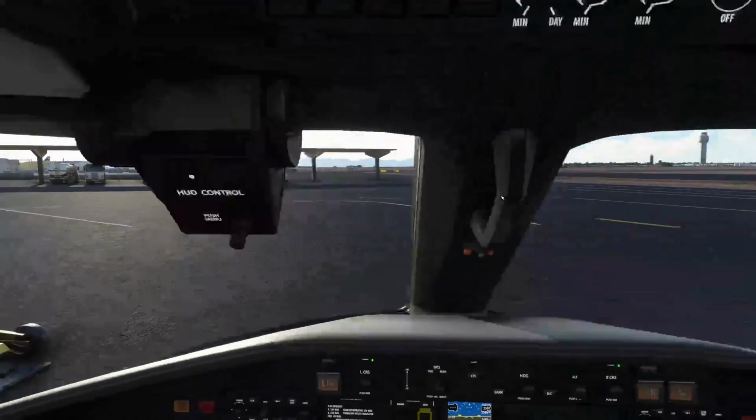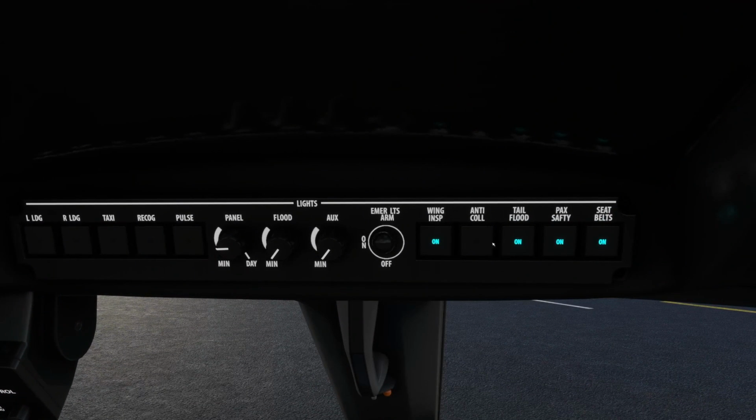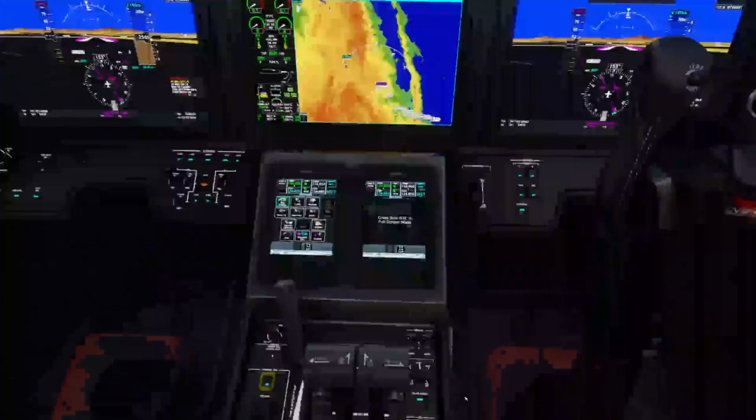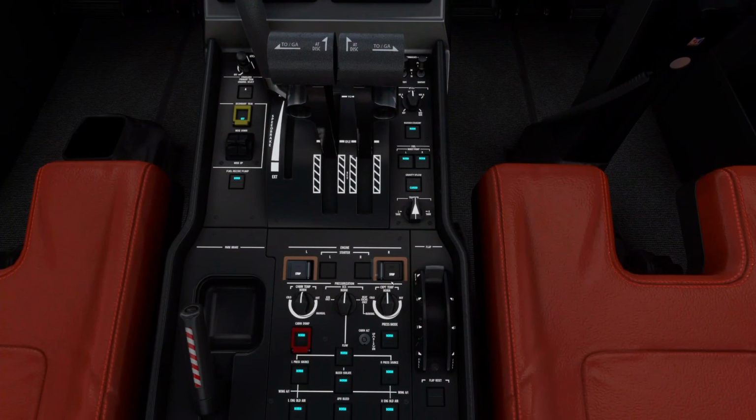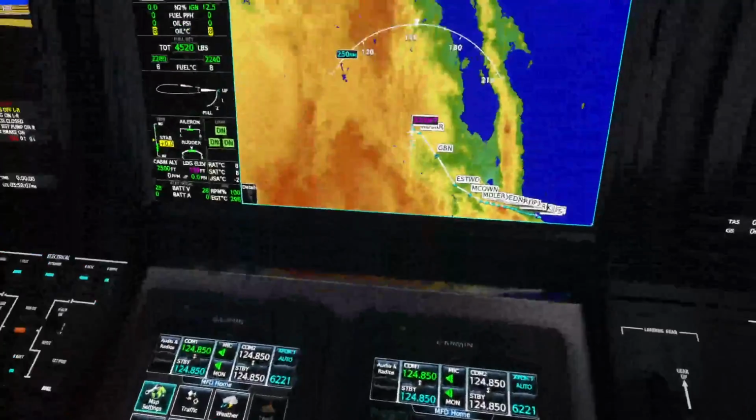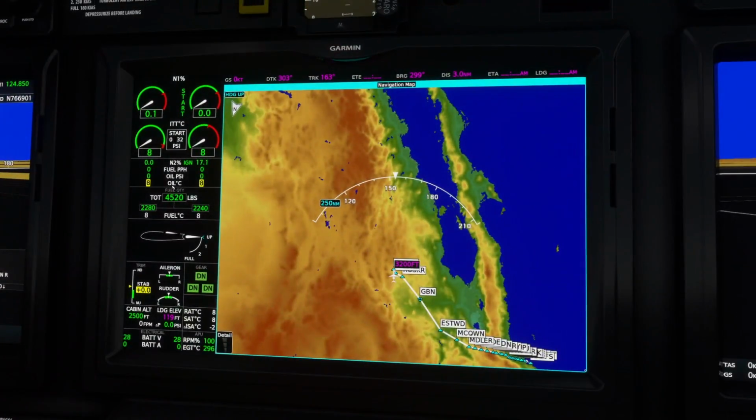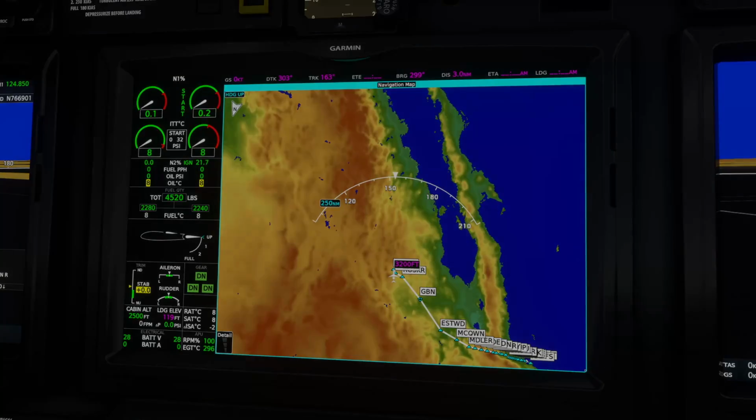So, let's go up top. And we're going to turn those anti-collision lights on, let the world know, hey, the plane is getting ready to start. I would not try to cook a hot dog right now. And stepping on back here, this part is very simple. Open up the cover, hit the start switch, or the run switch, and then hit the start switch. Okay, and from here, we will be monitoring engine performance right here. Once the engine reaches idle, we'll start number 1.